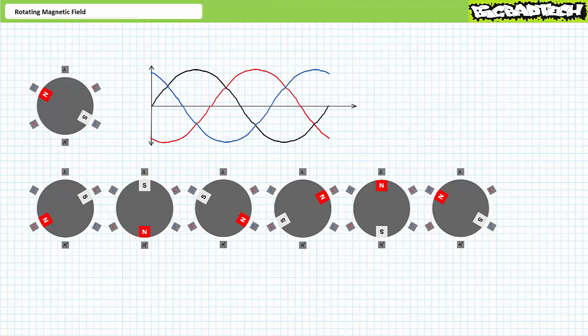Customarily, one swaps L1 with L2. However, as we demonstrated, swapping L2 with L3 works equally as well. For the doubtful among you, given the present configuration, I invite you to swap any two phase sequences with one another and perform the same iterative analysis. Seriously, swap any two phases and it will reverse. L1 with L2, L2 with L3, or L3 with L1. Regardless of the choice you make, so long as you only swap two, you should see the field return to clockwise rotation.